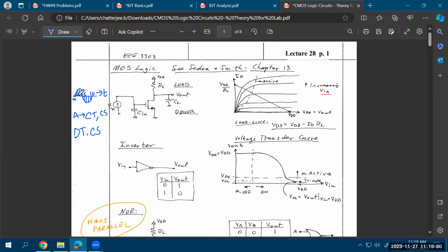But the value of the signal is not discrete. It may be 1.304. It may be 5.67219, and so on. You just have more and more numbers to represent the actual value of the signal. So the signal is still in the continuous domain. That is called discrete time and continuous signal if you have sampled a sine wave.